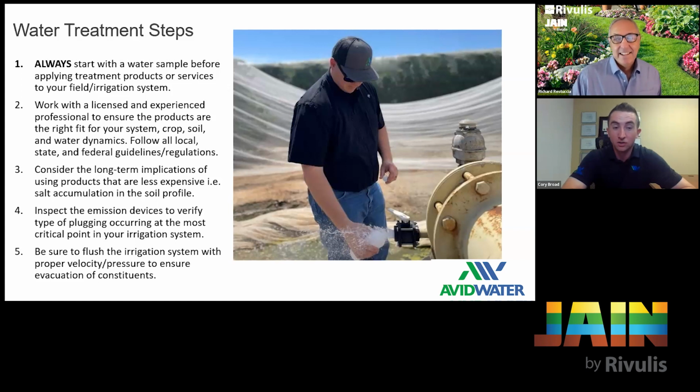I think going back and looking at the flow meter, going back and looking at the pressure. Hey, Richard, your flow's dropping. Okay, well, if the field flow is supposed to be 1,000 gallons a minute and it's flowing 998, I think we're okay. If it's flowing 990, we're probably still fine. But all of a sudden, when it's 900, well, that's 10%. And then now we're going down a bit of a spiral. So I think there are always early indicators. It's just how intensely you're looking for them.